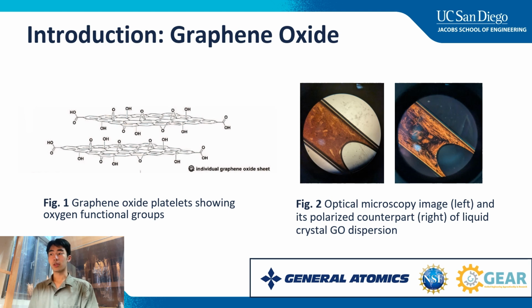My research this summer involved exploring the viscoelastic properties of graphene oxide, which is a property given relatively less attention in this field. Specifically, I fabricated 6 different samples of graphene oxide thin films and measured their damping properties via dynamic mechanical analysis.